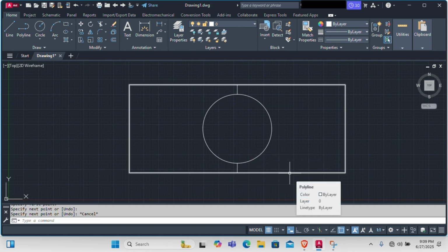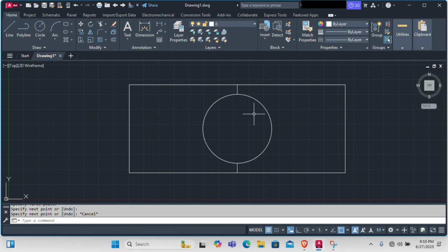Now let's say this is your layer 1, this is your layer 2, and this is your see-through hole as usual. So to represent two different layers, you have to have different hatches. So let us add these with different types of hatches or different patterns.